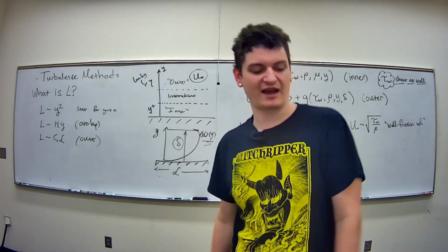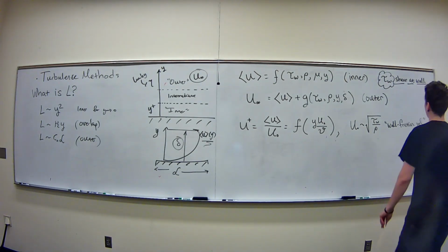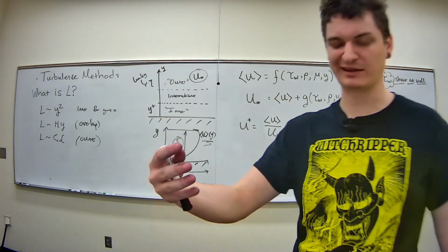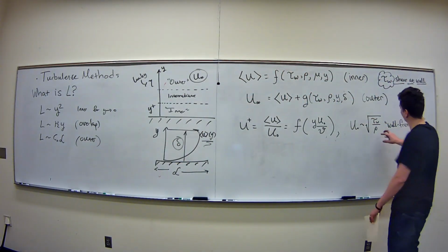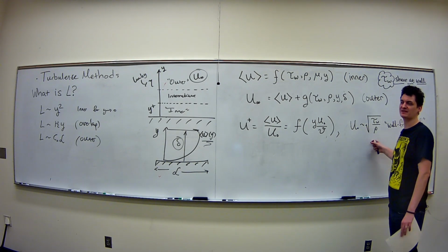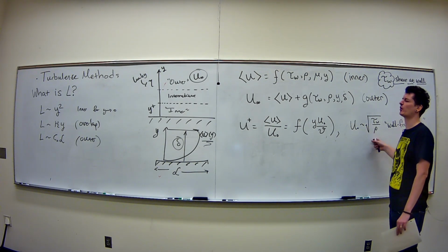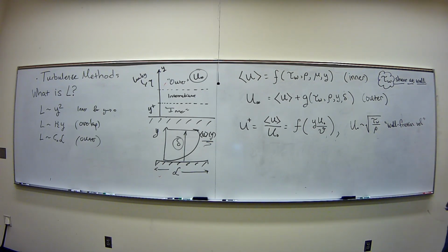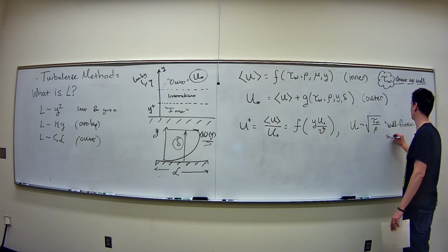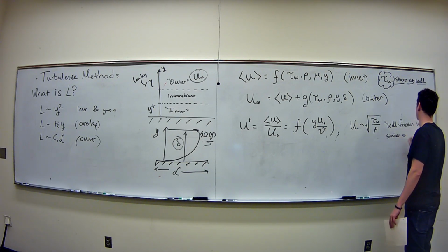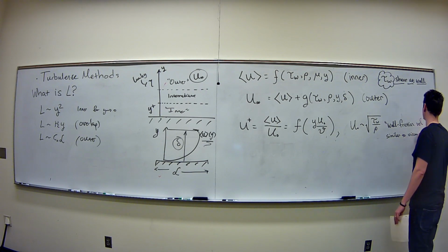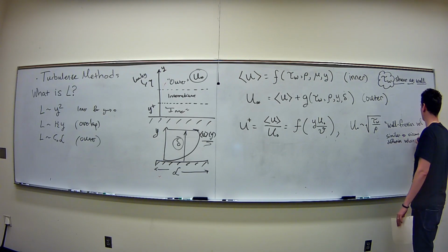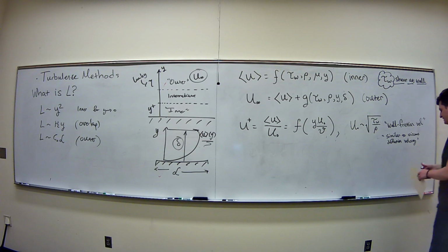It's just the idea that this is now the diffusion of momentum. So that's really the clearest sort of scale that you have, the idea that before I was looking at the diffusion due to viscosity of momentum, okay? And now this scale is the momentum diffusion, but through the forces of turbulent stresses. You interpret that how you want, right? So it's very similar to that viscous diffusion velocity.